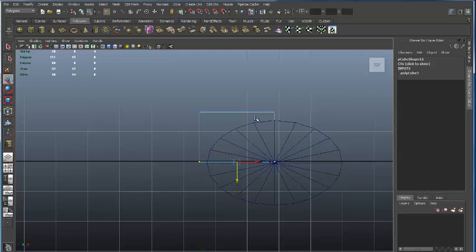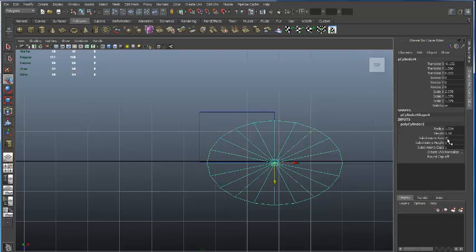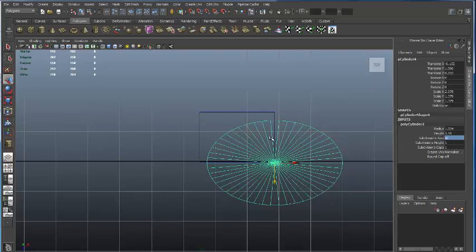There's some jagged edges in there. Do you see that? I don't really have a nice smooth transition. So what I'm going to do is select that object right now, go into independent selection, go to inputs here, and I'm going to really punch up the subdivisions to about 40 because I want to have a nice smooth effect happening right in there, right? Heck, I could even go to 50 if I want, because I'm going to lose this object. I want to have a nice smooth transition in there.